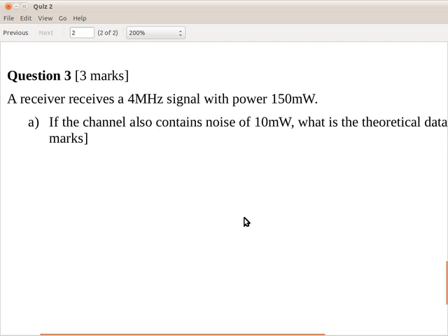15, I think you're close. Of 15, multiply by 10. Okay. So remember, decibels is just 10 times the logarithm in base 10 of the power ratio. Our ratio of power levels is simply signal divided by noise, which has an absolute value of 15.